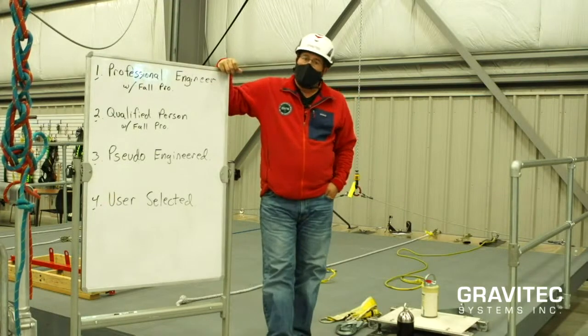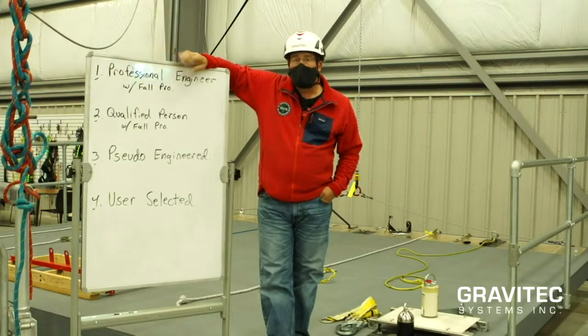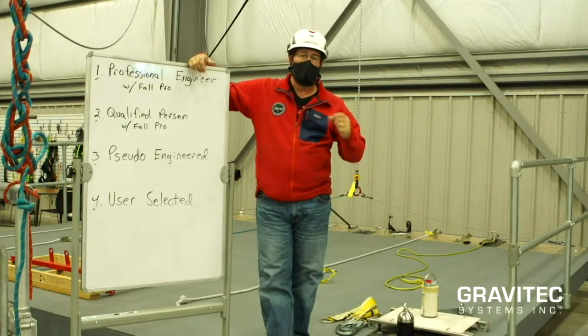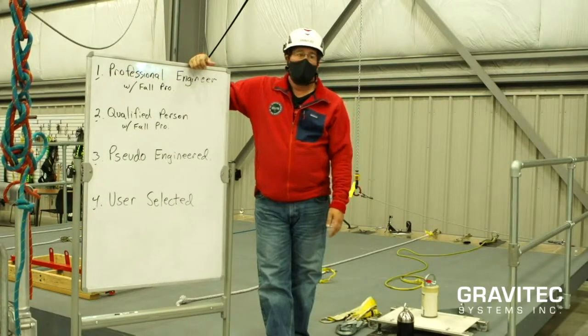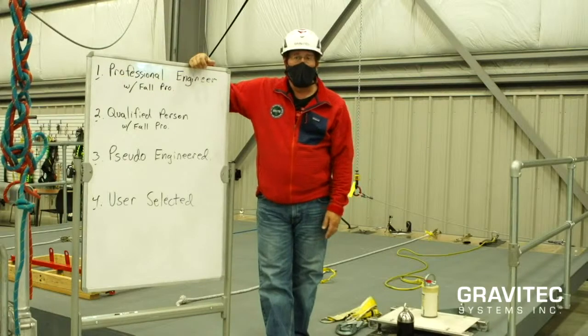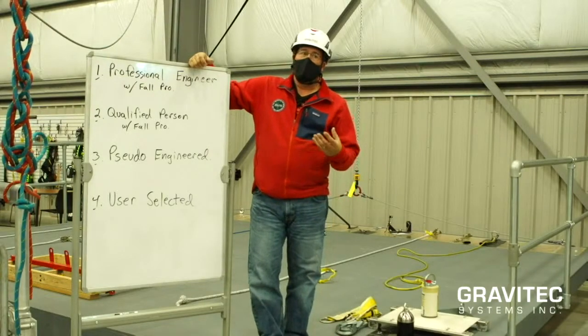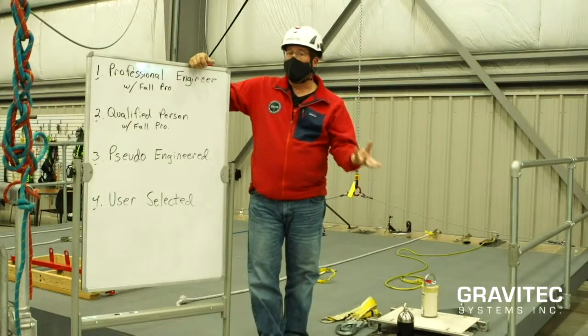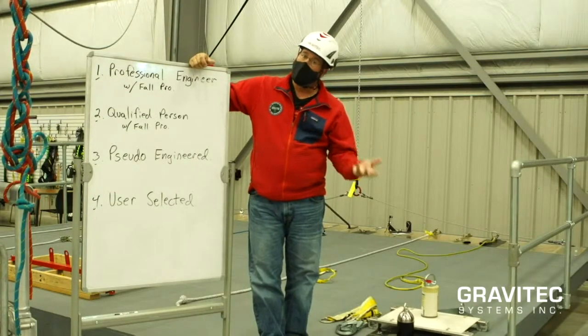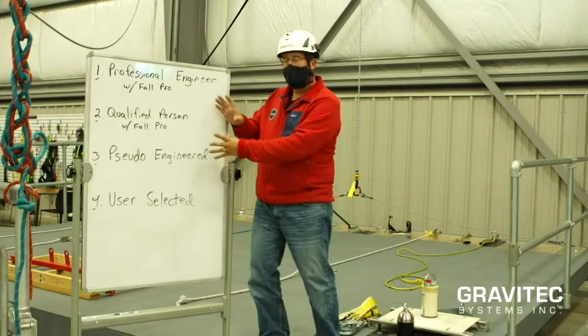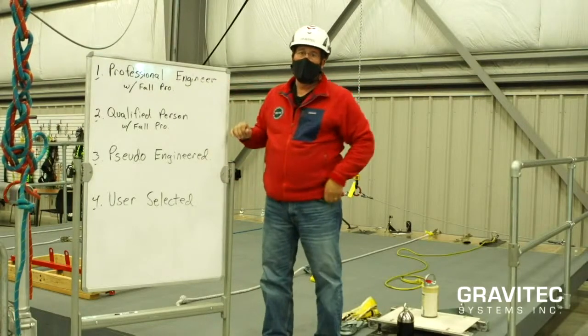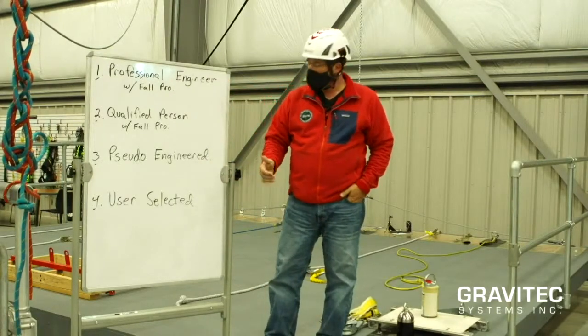Currently, Subpart D requires engineered anchors on the rooftops of buildings, anything that's going to be connected to a rope descent system. The IWCA, now defunct window cleaning standard, you're starting to see them included in architectural drawings as buildings are being built. So the whole world is trending toward engineered anchors, recognizing we're not there yet.